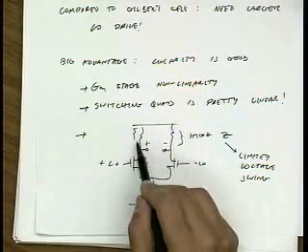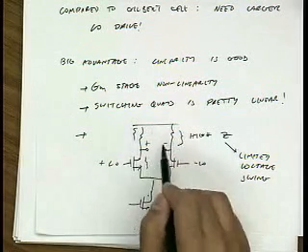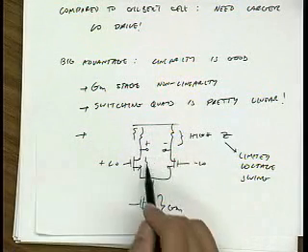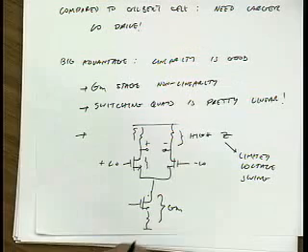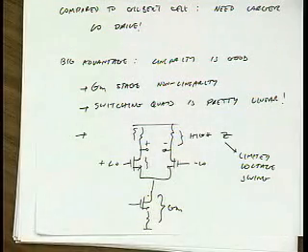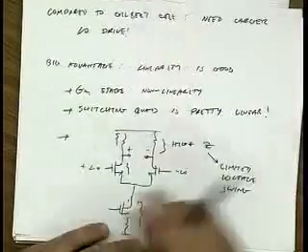Even if I use an inductor as a load here, I still have the headroom of these two devices. And recall that the output here is at IF frequency, at a lower frequency. So I would need a very large inductor to act like a low-pass filter, which is usually not practical for a low IF system. Okay, any questions about that?